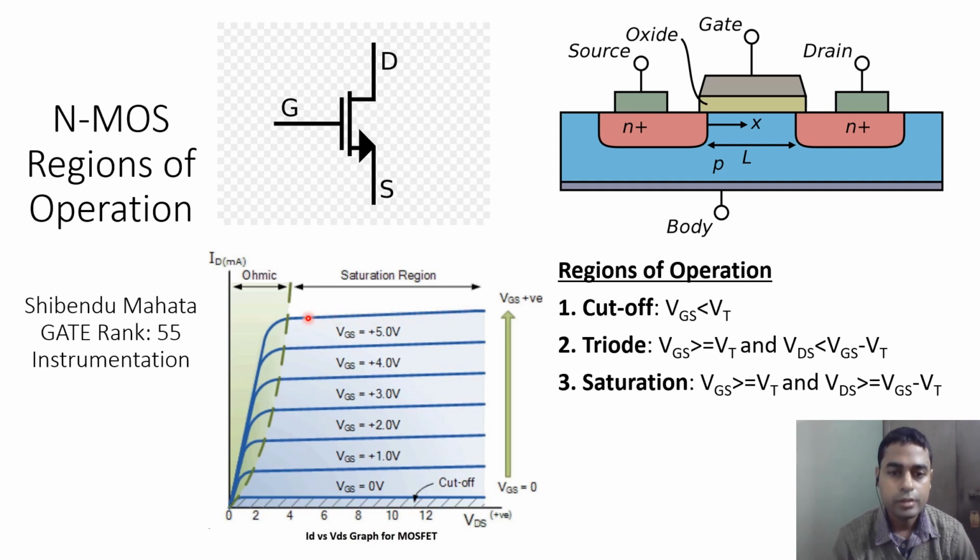So here, this is a practical diagram for the VDS versus ID characteristic. So this implies that in this region, we can model the N-MOSFET as a current source along with a resistance in parallel to it, although the value of that resistance will be pretty high. In an ideal case, these lines will be absolutely parallel to the x-axis and you get an ideal current source.